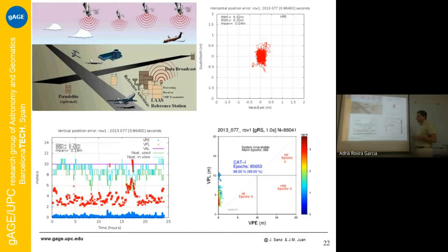And we check, remember we have 4 metrics. We have accuracy, but also we have the integrity, and then we have the protection levels. You can see that the actual error is bounded, is protected by this value, the protection level, so that the errors are small. If we have a drop of satellites, maybe we increase a little bit the error, but always bounded by the protection level.